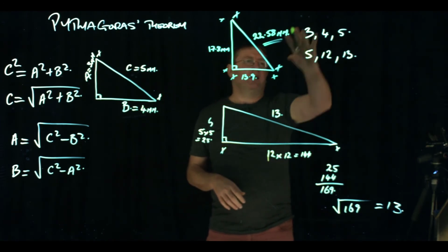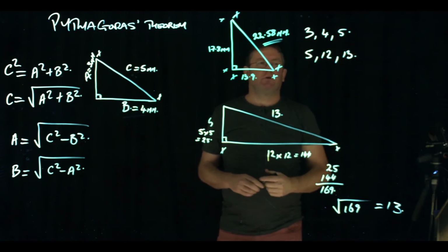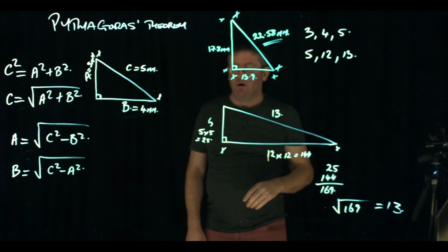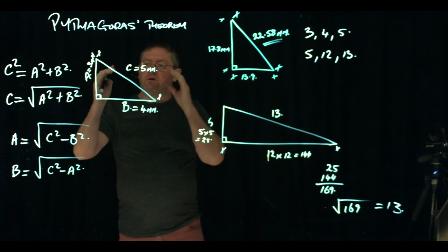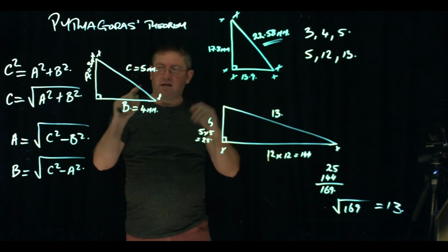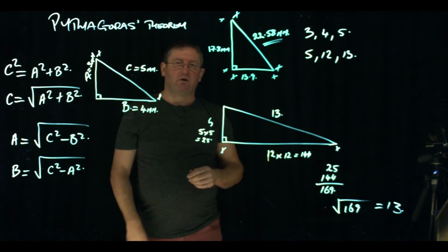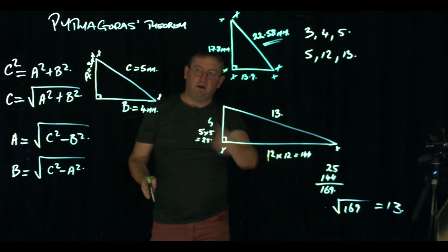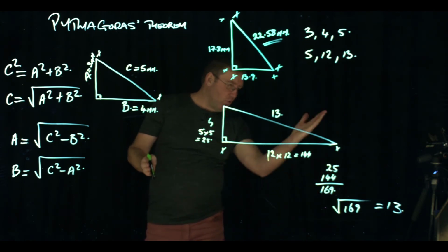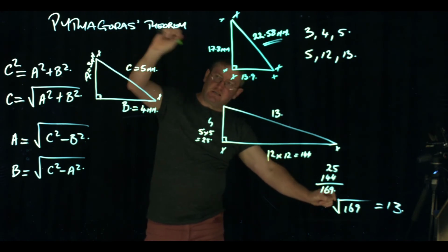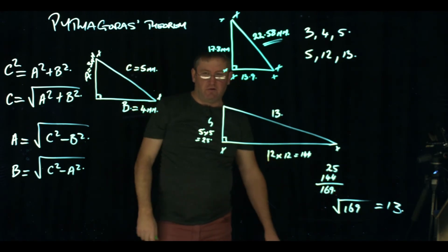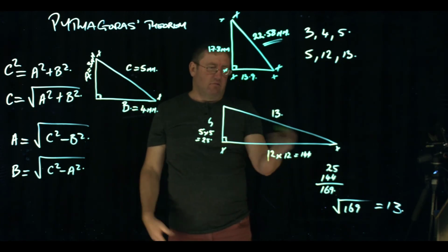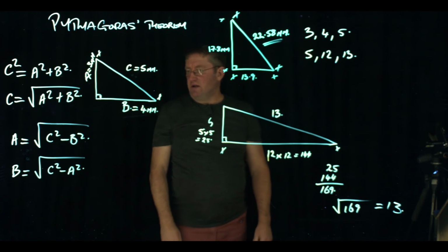You can actually use different Pythagorean triples if you look them up on the internet. There's hundreds of them on Wikipedia if you want to use them. Or you could just have a basic understanding of laying something out with a 3, 4, 5 triangle. You don't even have to do a calculation. You just measure 3 units one way, 4 the other way, run a tape across, and pull one leg in until the 5 hits the outside point of the 3 and the outside point of the 4. That gives you an absolute square.